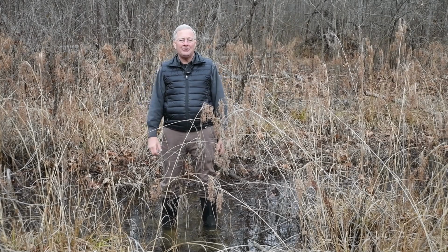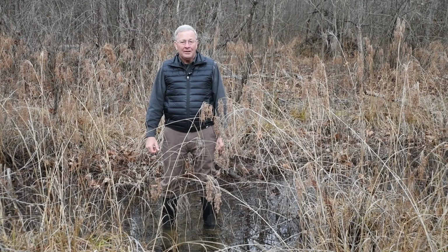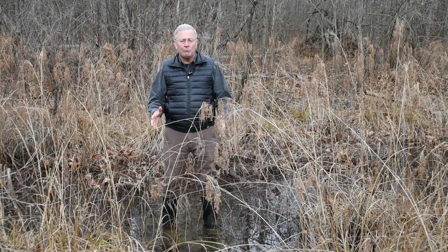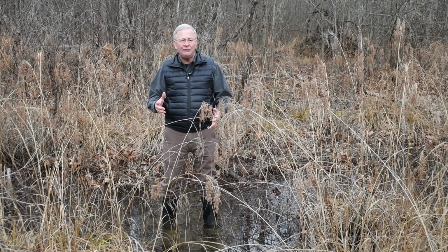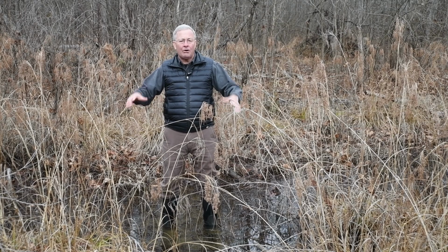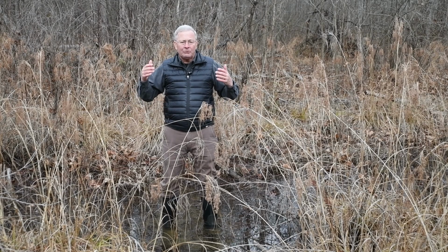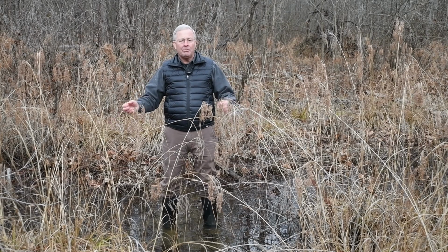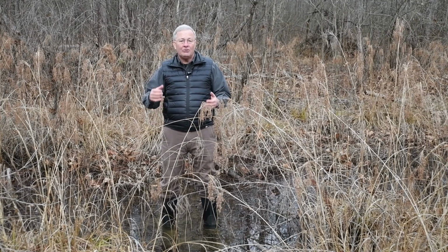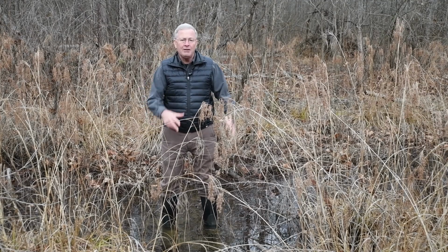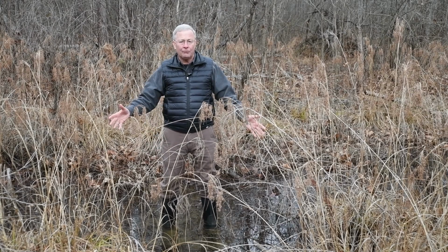I'm now going to take you to the Dix River Wetland and Stream Restoration Project in Lincoln County, Kentucky. This is an amazing project where we use groundwater dams to raise the elevation of groundwater 26 feet over a 72-acre cornfield. The project was so successful that not only did we restore this complex of wetlands, but we were able to take ditches with an intermittent flow of water and then turn them into naturally appearing streams with a perennial flow of water. These groundwater dams work, and I hope you enjoy seeing these photos.